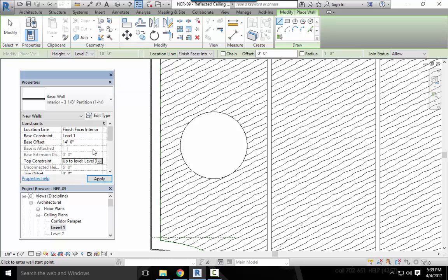With the wall command still running, click the pick line icon on the draw panel. You're going to have to draw this in 2 pieces. It won't do it as one piece. Mouse over the radial, a blue line appears. Make sure it's the inside of the opening. Then press the tab key twice. It's still 2 lines. Trust me. And click. There you go.